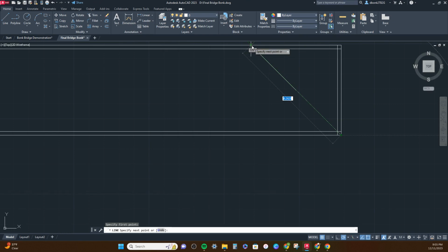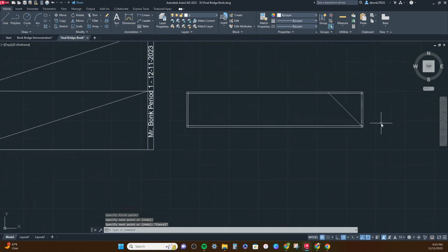Ooh. Yeah, we actually want to finish this off up at the top to trim. We're going to do this on both sides. Draw a line going up at an angle. It'll snap. The green dotted line will show up at 45 degrees. Hit the escape key when you're done. All right, and now what you'll do is trim away what you don't need. Click the trim tool and you can just draw a line through all this stuff.